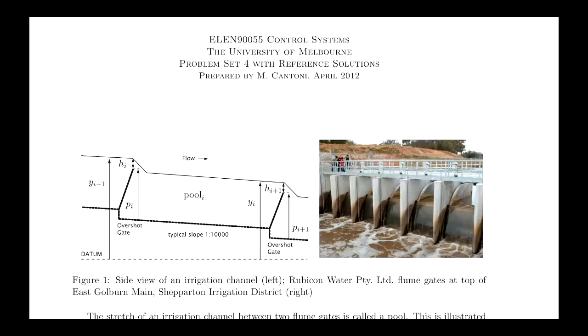And that's an important operational objective because your capacity to supply flow further downstream or to end users via supply points at the end of these pools under the power of gravity is determined by the water level. Okay, if you like, the water level is the amount of potential energy stored available to push water further downstream or onto farms at the supply points.